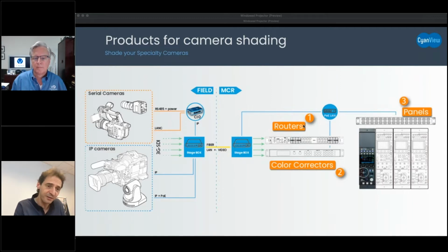You can still line up 4 RCPs if you want to control 4 cameras, and I would say this makes sense whenever you still want to control 4 cameras at the same time with 2 hands. So you are going to look at a multi-viewer. And in that case, if you want to be able to lively paint those 4 without having to switch, this is a way where it makes sense to have RCPs. I will come on a slide just explaining another type where it makes sense.